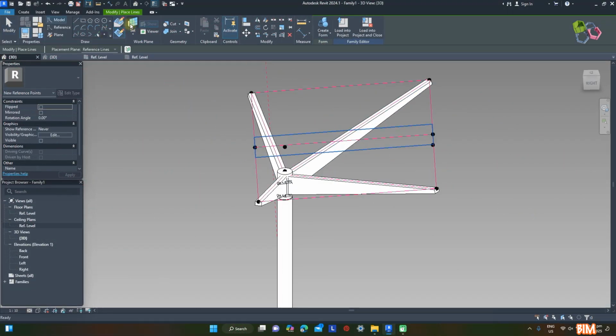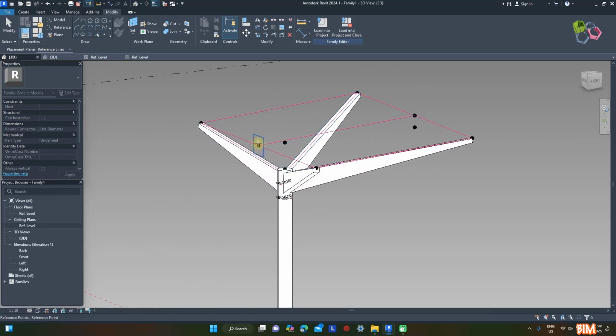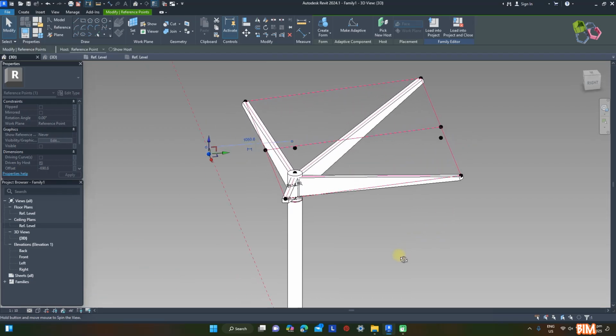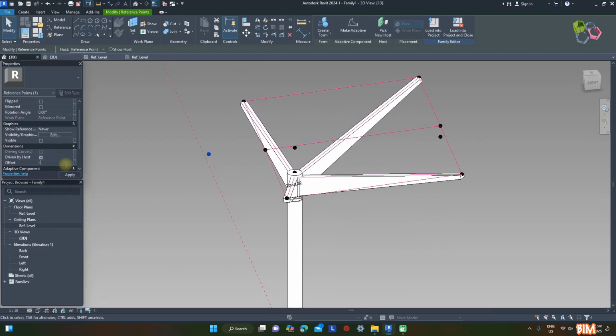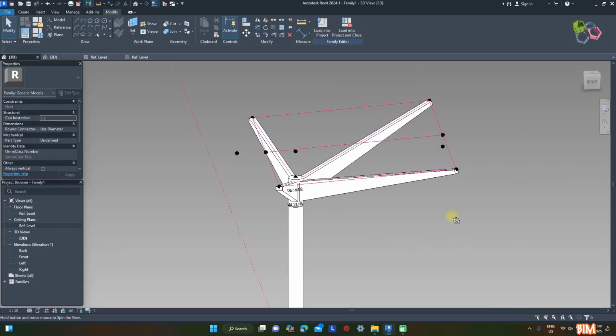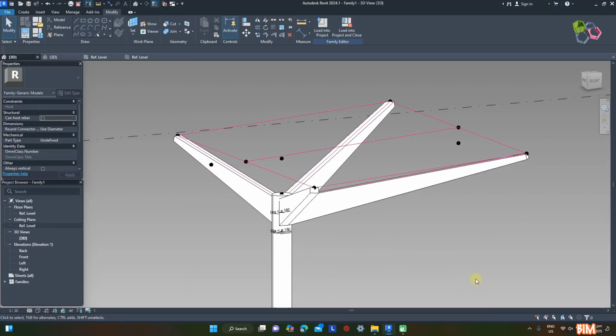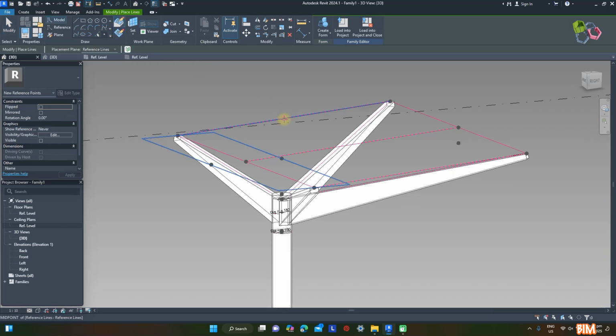Reference to roof shape. Add a point to extend the middle reference line with a fixed negative 350 mm for the curved roof extension behind. For the curved roof, create each point at mid position for two sides and the middle reference line.